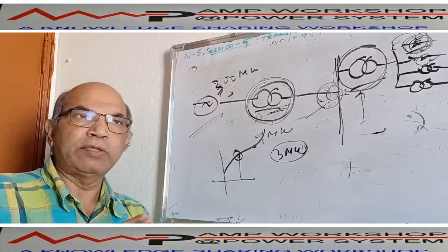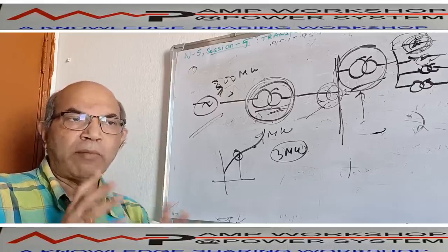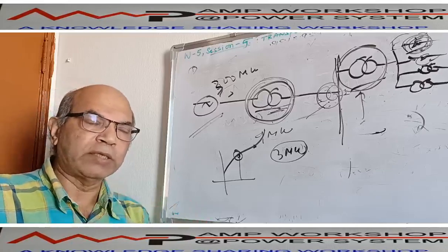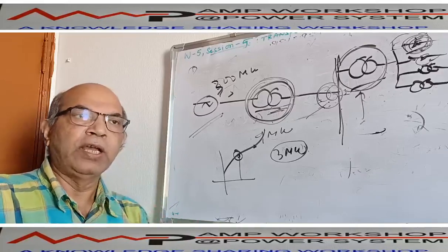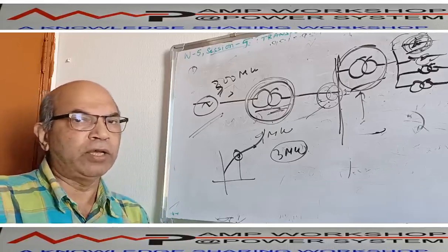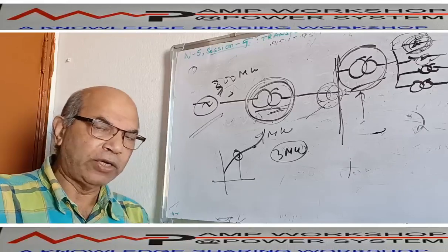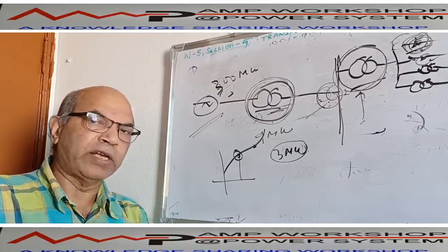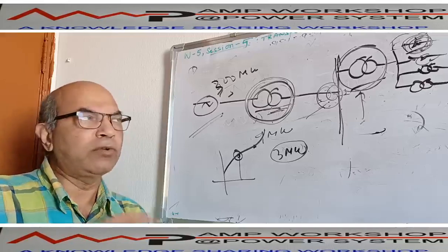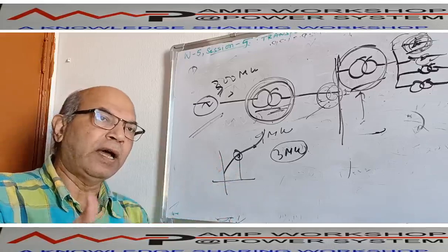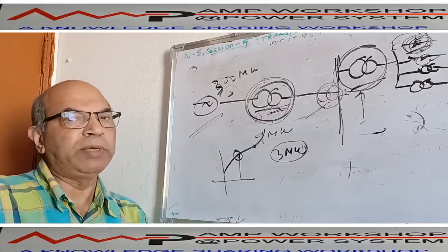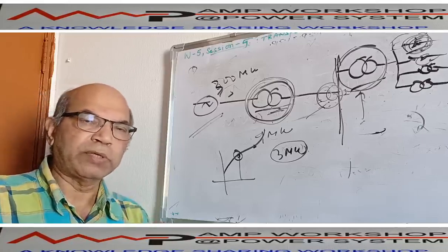But in the end, it is recommended to avoid overloading of the transformer as far as practicable, because overloading will deteriorate the insulation and reduce the life of the transformer. That's why frequent overloading should always be avoided, and continuous overloading of the transformer shall not be done at any time. Only temporary overloading during motor starting could be done, considering the history of the transformer. So this is all about transformer sizing.